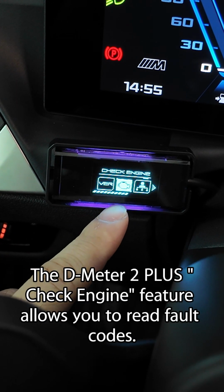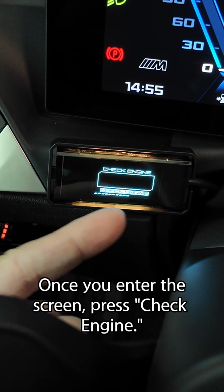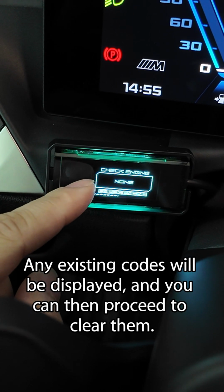The Dimeter Plus check engine feature allows you to read fault codes. Once you enter the screen, press check engine. Any existing codes will be displayed, and you can then proceed to clear them.